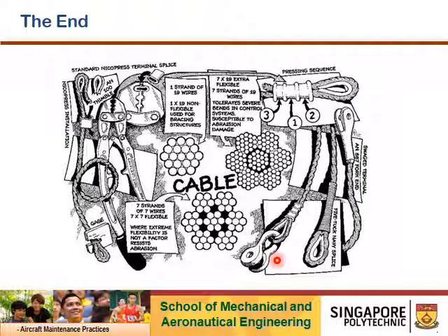with improvement of technology and aircraft design, this mechanical attachment or command is being replaced by computers with fly-by-wire. So instead of mechanical control, it is now an electrical signal to command the flight controls to move. Then again, mechanical control will act as a backup, like on the 777. No matter what, the authority will want the aircraft manufacturer to employ fail-safe redundancy.